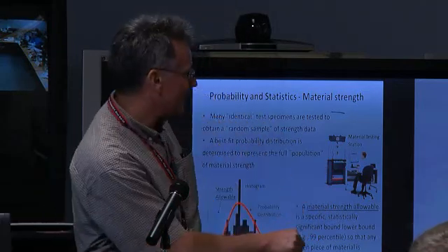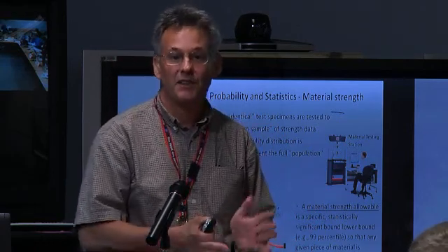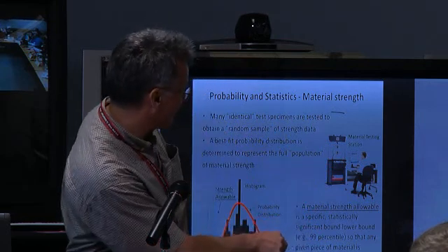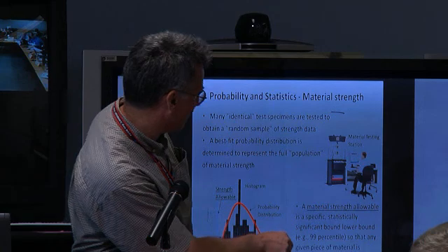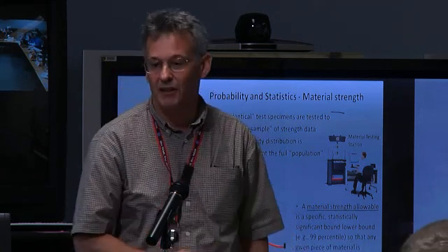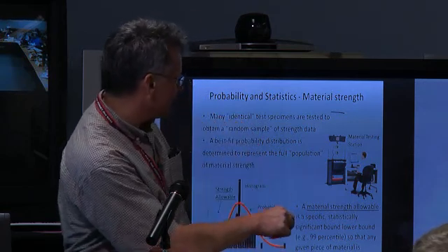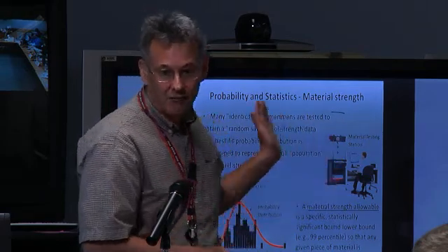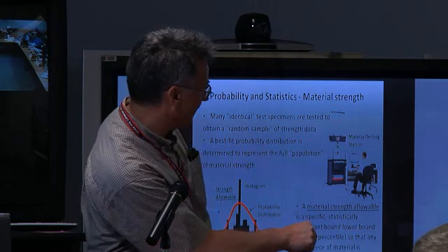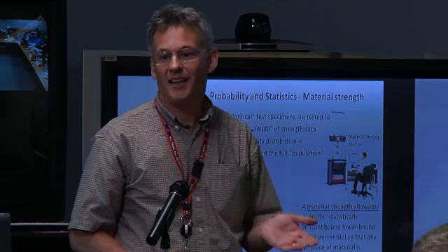So getting this kind of data, though, says, okay, I can run statistics on it. I can say, give me a probability where this thing won't fail. Running statistics, I could say, well, if I go down to 27,000 pounds per square inch, if I take the area of this curve, 99% of the area is to the right of that. It's at a higher stress. So I have only a 1% chance of failing at that stress or lower. That's not bad. That's better.